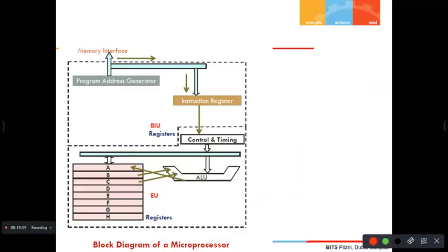Suppose you want to store 8 bits, how many D flip-flops do you require? 8. How are they connected? Suppose you want a parallel-in, parallel-out shift register, how do you make the connections? Can you imagine that connection of registers? A single input line connected to 4 flip-flops. Exactly. That is parallel in, parallel out.